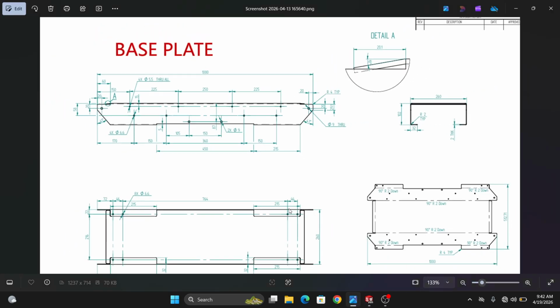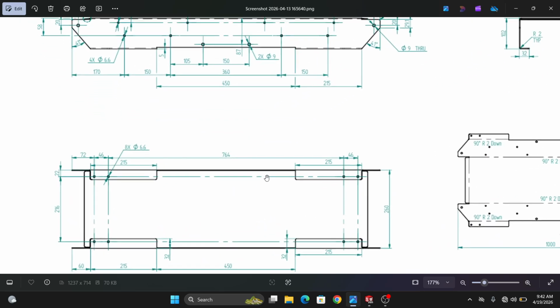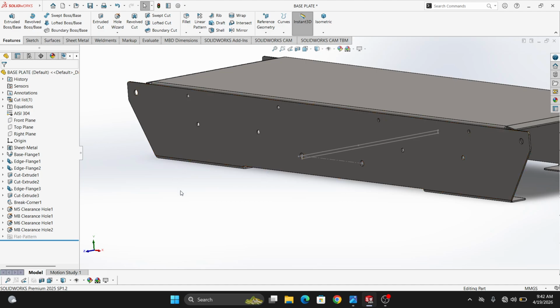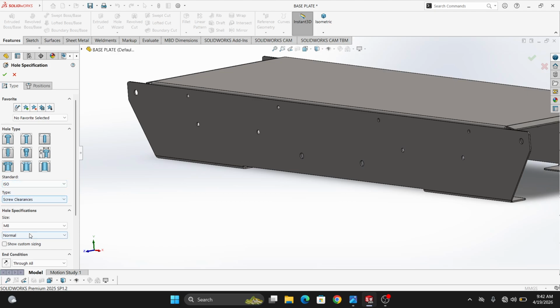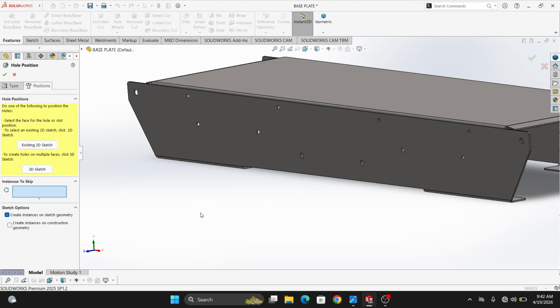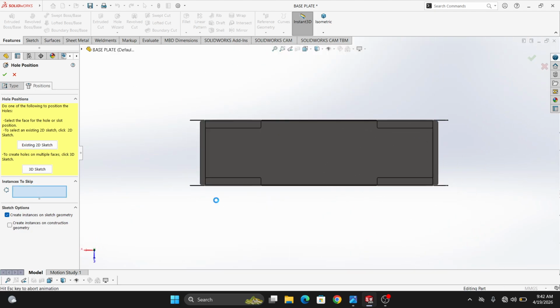Okay. Again there are 4 holes, 6.6 through, and there is 46, and 74. Select first, always add 6.6. That is M5. M5 clearance hole is there. Select M5. Go downside here. Down to 5.5. We need M6. 6.6. Select position. Select this space. Okay.